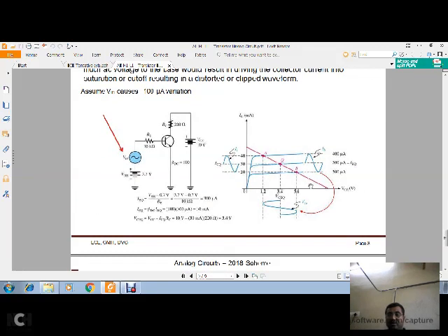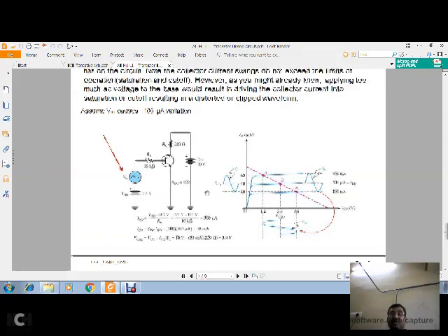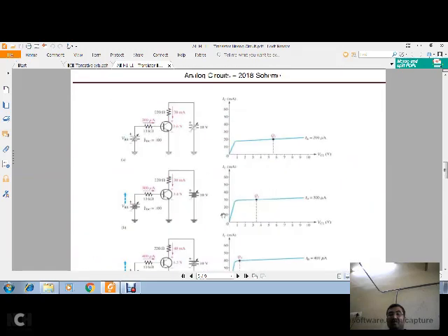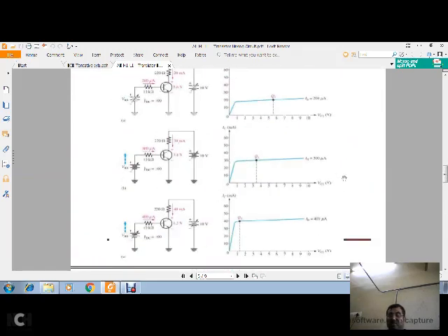Here you can see, yes. Now assume I considered the IB value as 300 microamperes. If I am not considering 200 and 400 microamperes, it means I am going to apply VBB and take RB such that the current flowing through the base of the transistor is 300 microamperes. That means it is the middle case, case 2. Take this case. I am going to take 300 microamperes.